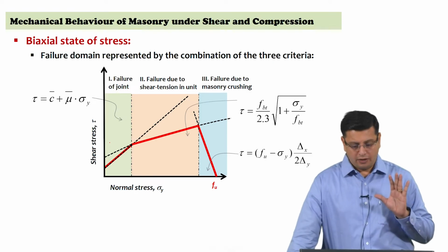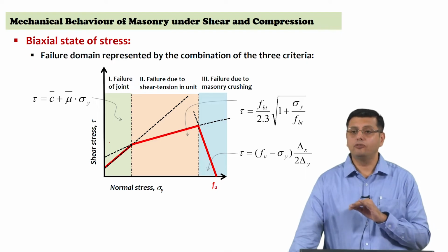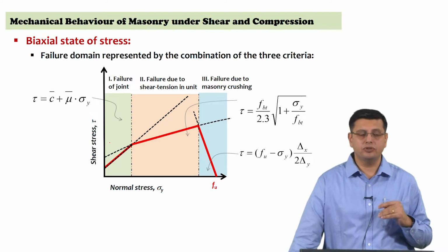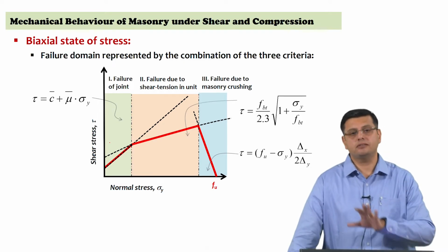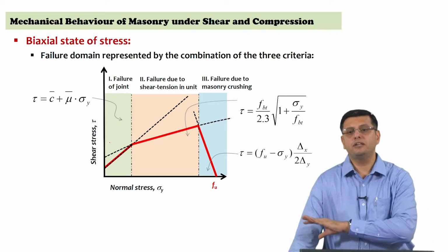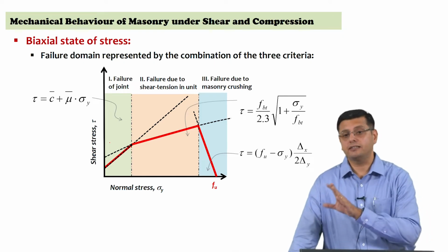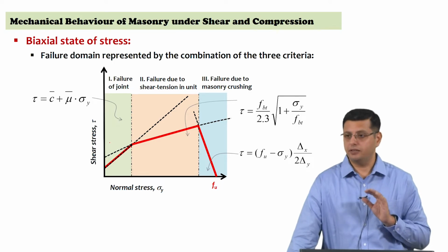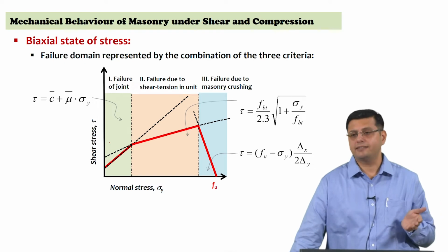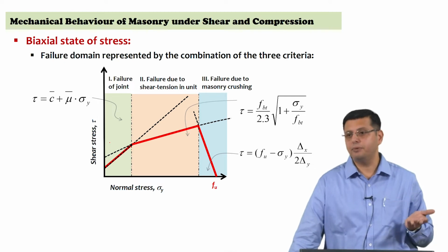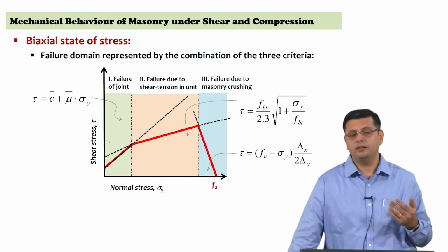So while we are defining this at the level of local stresses and relating it to the global stresses, this becomes the basis for us even later to establish, in terms of stress resultants, what is the lateral force axial force interaction in a masonry wall, right. You are familiar with axial force bending moment interaction, PM interactions, that we use for design in concrete.